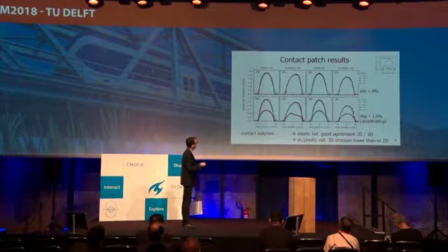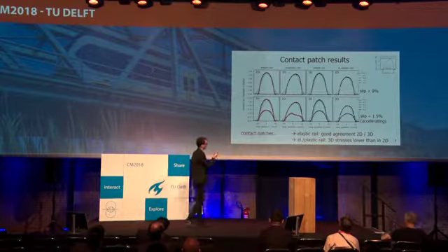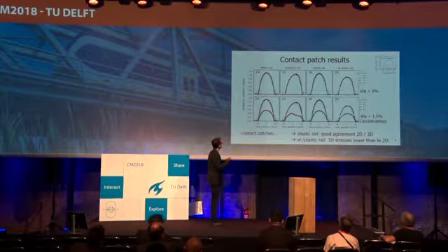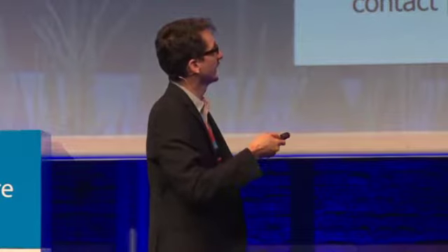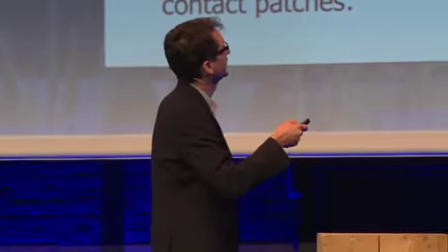If we introduce slip, we see we also have these shear or traction stresses here, and also the contact patch becomes a little bit asymmetric when we roll over it. What we also see here is the mesh dependency, and we see we get quite good and accurate contact patches if we already use 1 or 2 millimeters of mesh size. That's sufficient for that application.